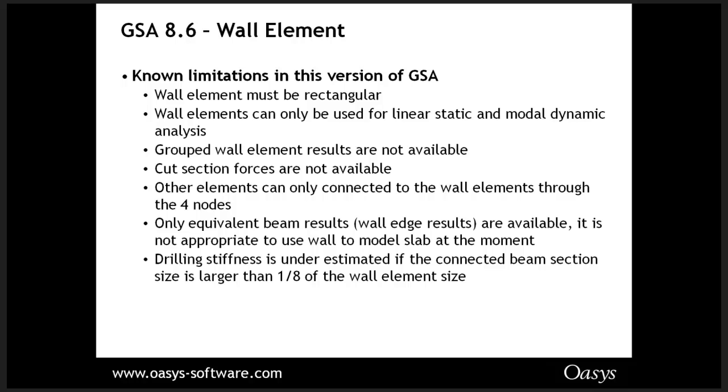The results are only available for the 4 edges that will be given by equivalent beams or wall sticks. So in the future, we are going to output results like stresses and moments inside the wall element, similar to a 2D element. With a shell element, you can get the forces and stresses inside the 2D element. But in the future, that will be available for wall elements as well.